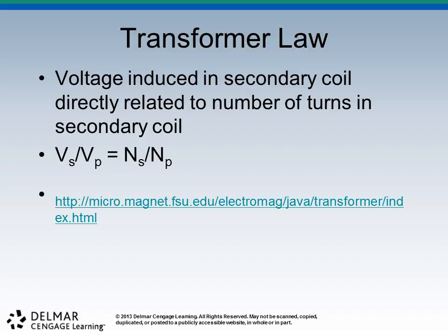You get it? When you manipulate your kV, what you're actually changing in real time is the voltage. You'll go from 40 volts to 50 volts, and that's your incoming primary voltage. Your outgoing secondary voltage will then be 40,000 volts or 50,000 volts. It's a little different ratio than what I just said, but that's easy enough for us to understand. We come in one side, we go out the other side many thousands of times greater. And we need those thousands of volts or kilovolts in order to induce the proper energy of our X-ray photons.